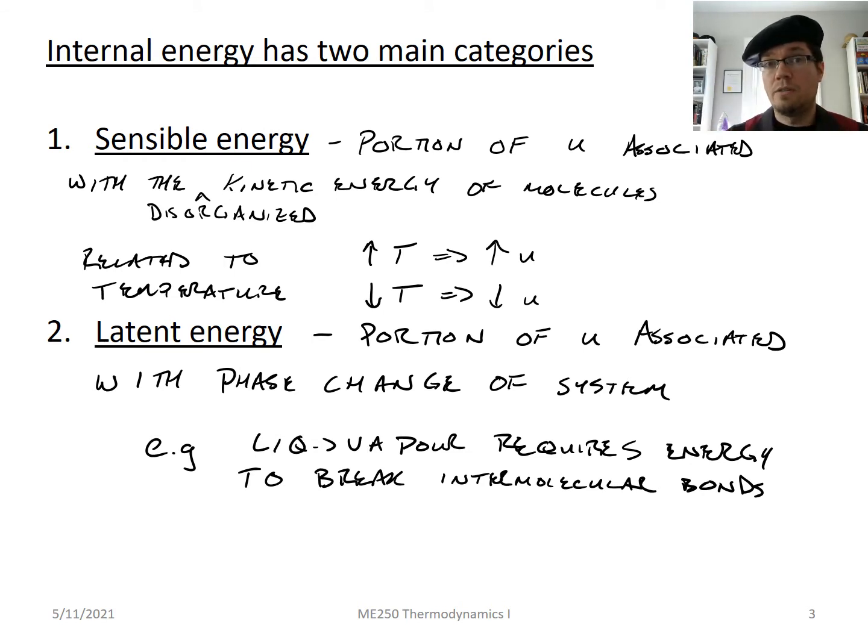Those molecules in the liquid phase still have intermolecular bonds, but not as strong, and they can move relative to each other. You add more energy to them, they break those bonds and zip off and become a gas with very little intermolecular bonds between each other. So that's the idea of latent energy. It's the energy that is stored in those bonds, and to break those bonds requires energy. If you reform those bonds, you recover energy, and that's phase change.